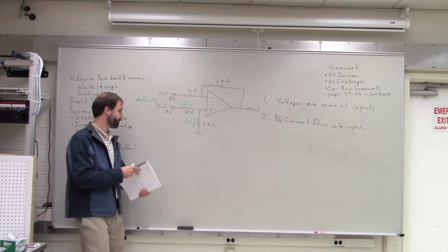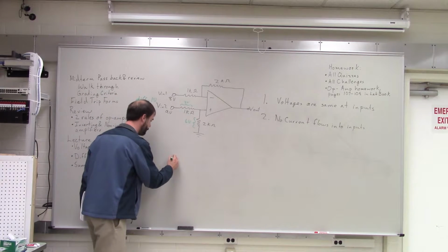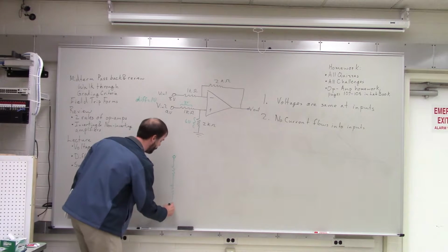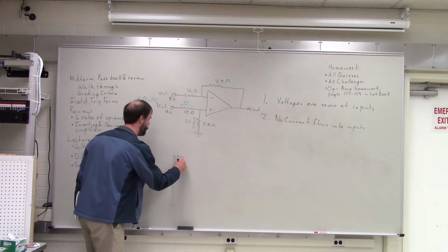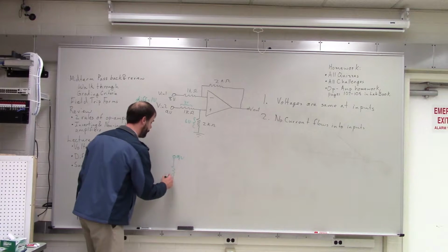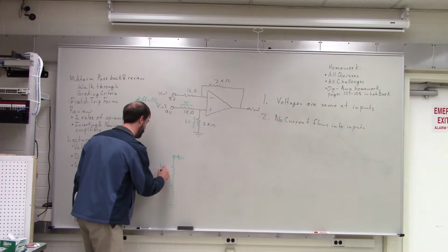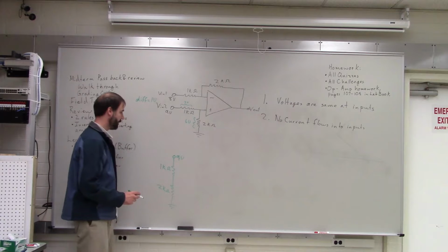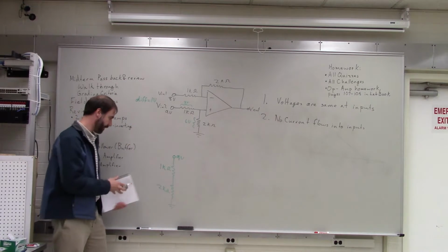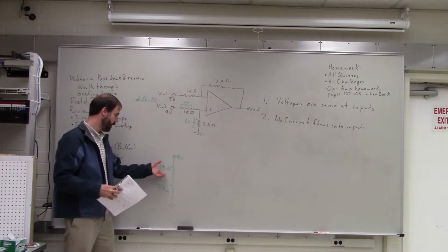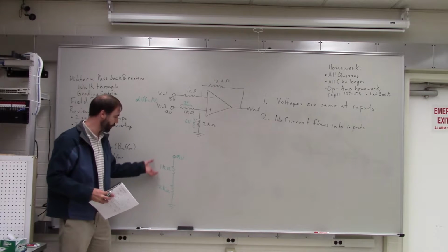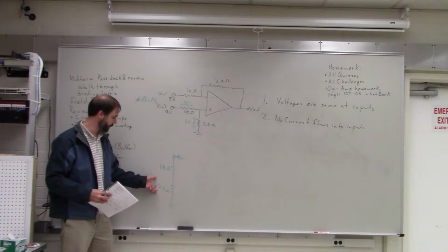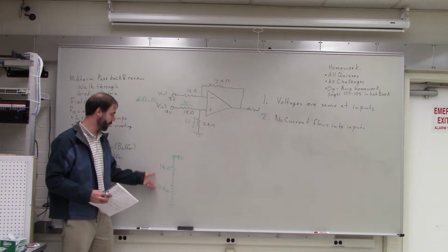Yeah, so basically we've got a situation like this. We've got a voltage divider, we've got 9 volts up here, 1 kilo ohm and 2 kilo ohms. Okay? And we remember that with the voltage divider, each one of these resistors gets a portion of the total voltage. So if they each had half of the total resistance, they would each get half of the total voltage.